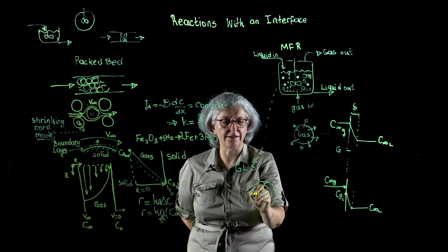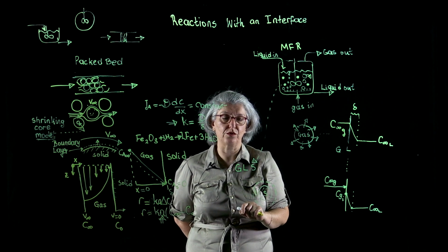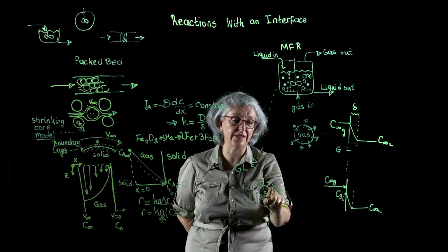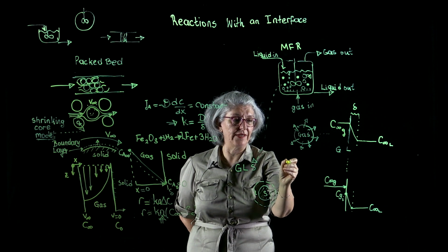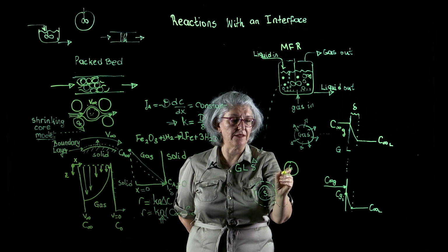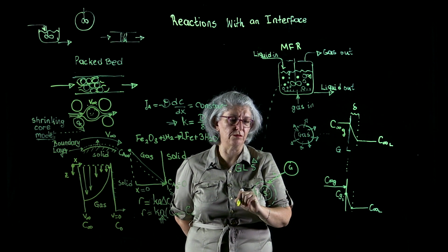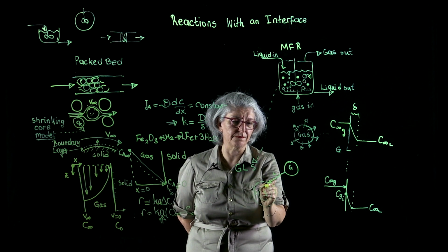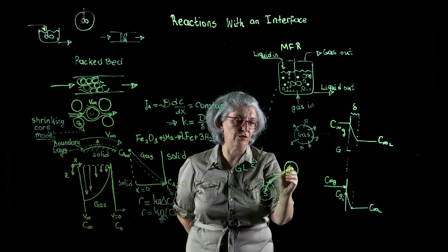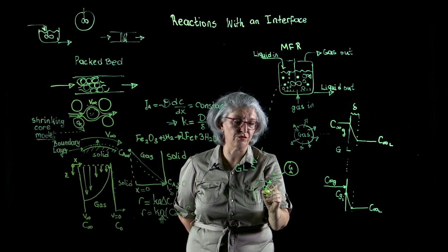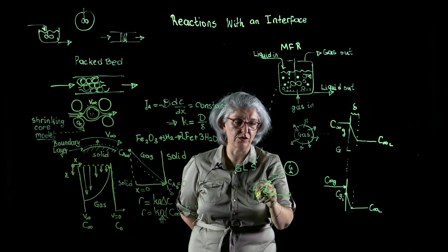All right. So here we have our liquid film, which we might just take that liquid film moves with the velocity of the solid particle. As far as the solid particle is concerned, that fluid film is stationary. And somewhere up here, we have a gas bubble, a gas molecule diffuses through the liquid by molecular motion, penetrates through the liquid film, penetrates through the solid catalyst, goes through a reaction, and let me call this reactant A, and the product has to move through the solid, move through the liquid boundary, and then go back to the bulk liquid as B.